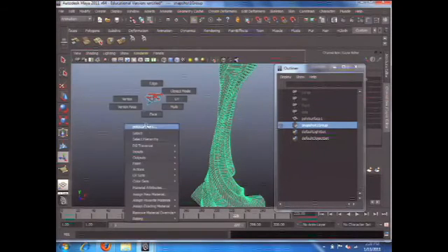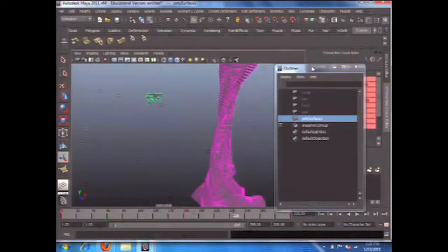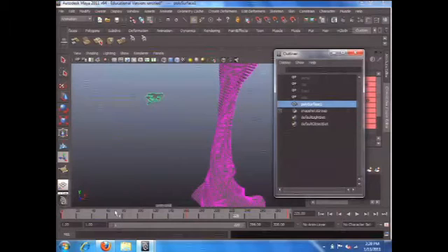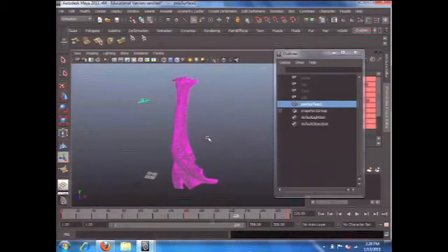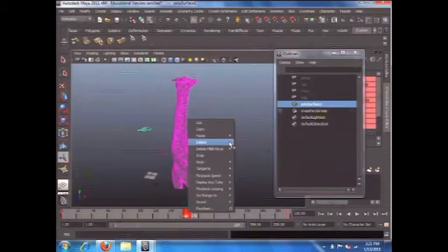You could control the timeline, the keyframes afterwards. For example, right now I have a couple of keyframes. But for some reason, if I don't like a particular keyframe, I can remove it. For example, I don't like this keyframe at frame 160. So I can hold shift, drag your mouse with the left button, and highlight this keyframe. Then I can right-click, delete.